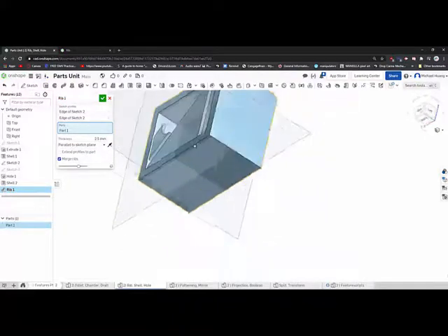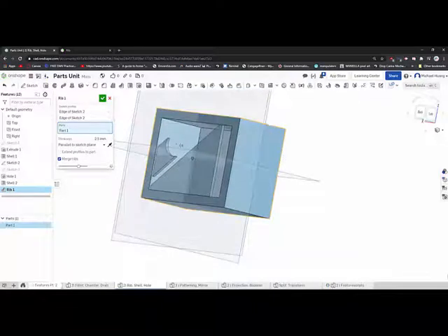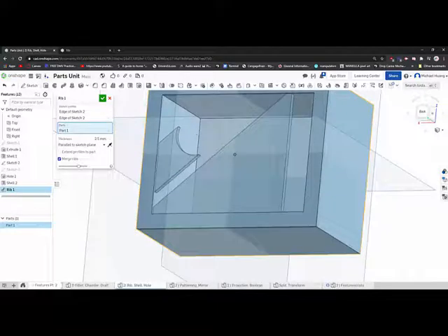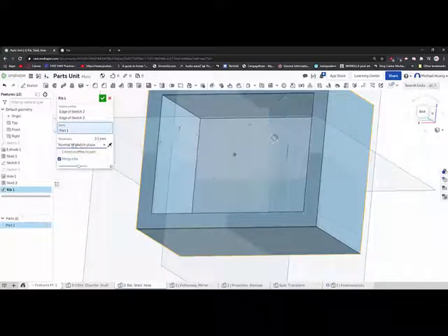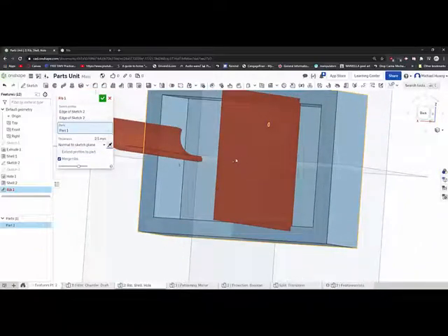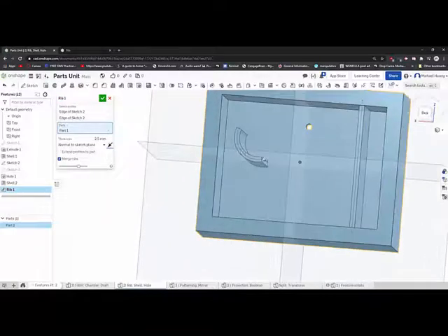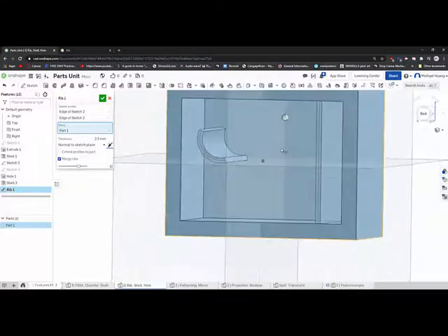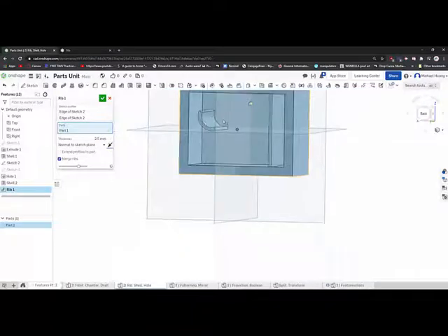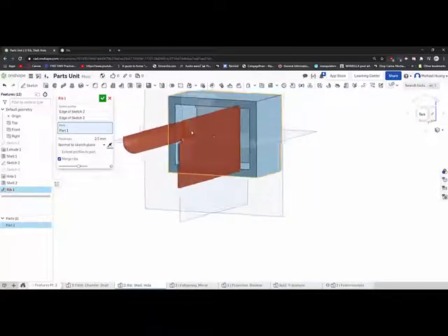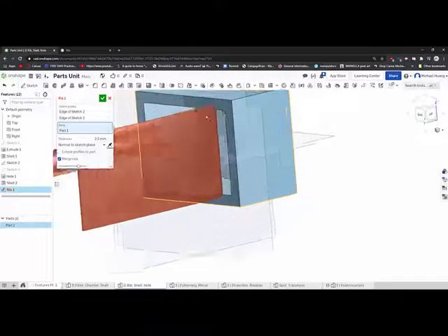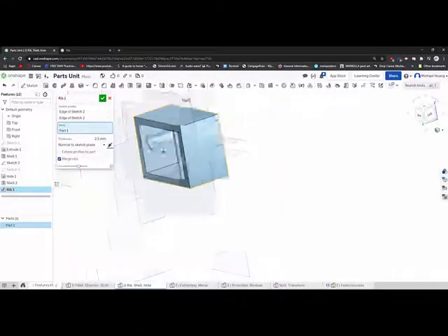And you'll see it's only like this because it doesn't know the direction of the ribs. What if I want my profiles to cut downwards into the shape, right? I'm going to click normal to sketch plane. Change the direction. So you'll see now it's cutting outwards. Change the direction, and that's going to actually create my ribs. Ribbing is an additive feature, so you're adding material. You're never going to be removing material. Okay, so that's why this doesn't work. There's nothing really to remove.